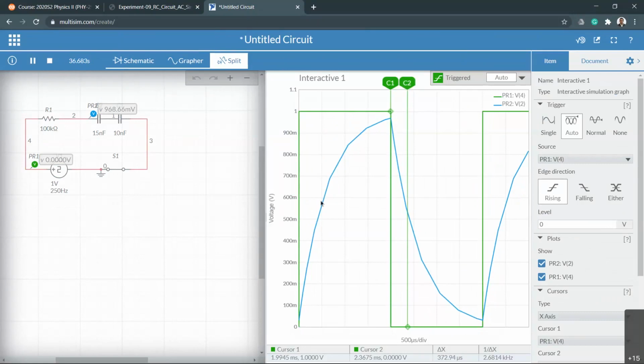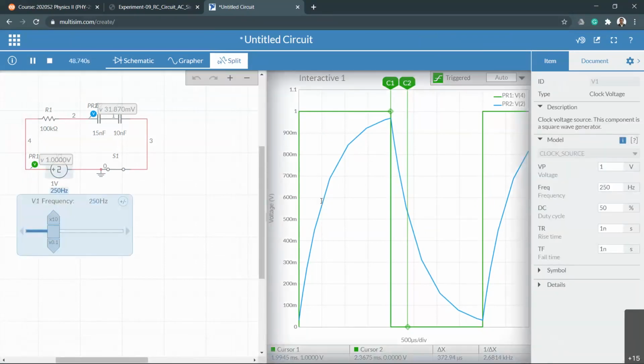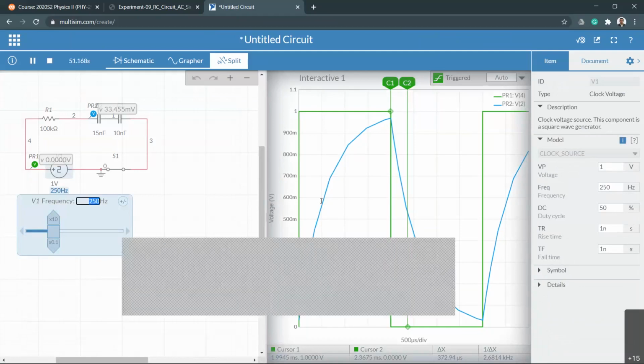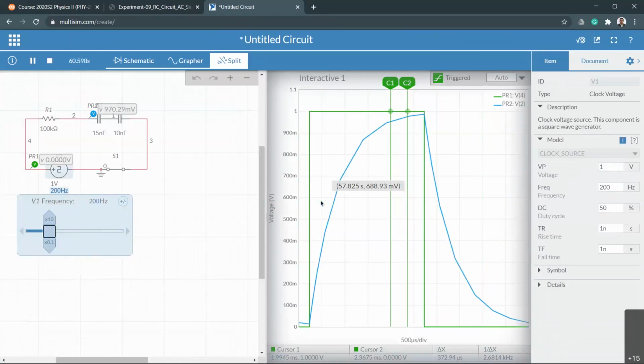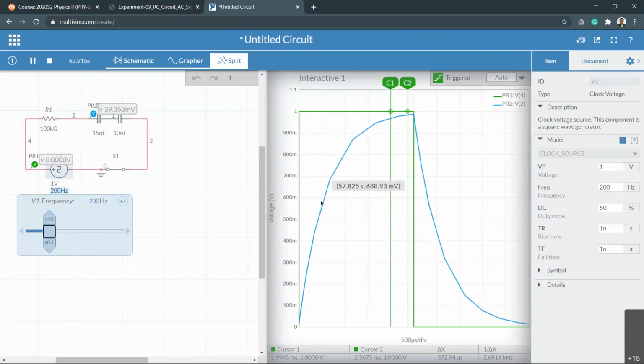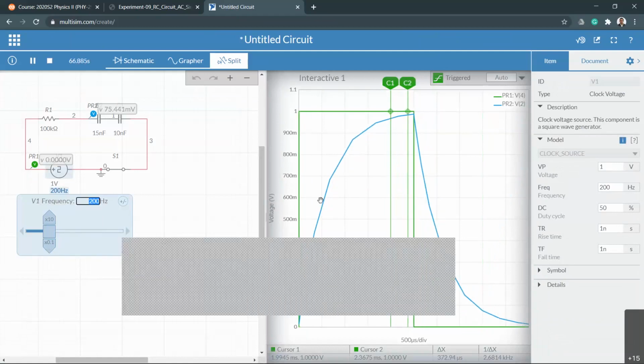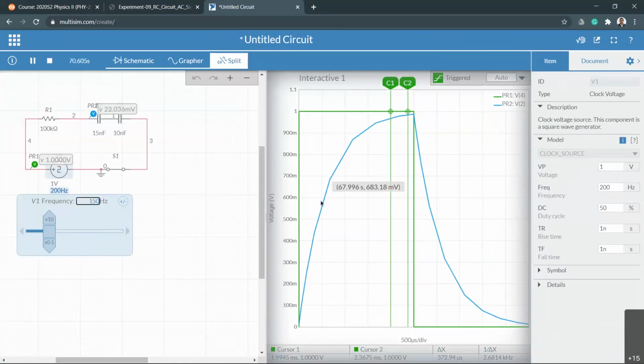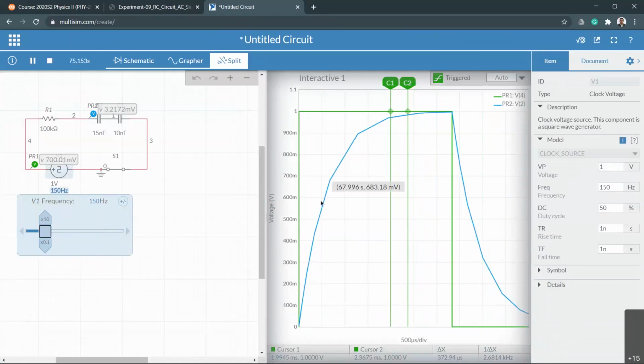Okay. Now you can see again, there is a little problem, right? You can see it's not charging enough, which means maybe I have to give enough time. So you can give enough time by decreasing the frequency, right? If you decrease the frequency, you can increase time. So let's decrease this frequency to maybe 200. See it reaching there, but not enough. Decrease more. Let's go back to like 150. Good enough. So see that? So that's the idea, okay? Good equation. So those are the fine adjustments.